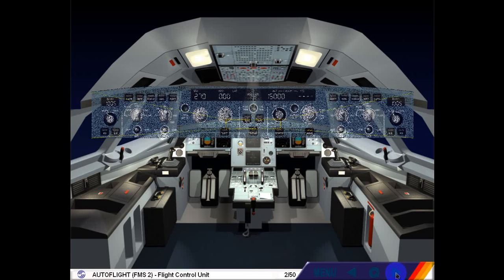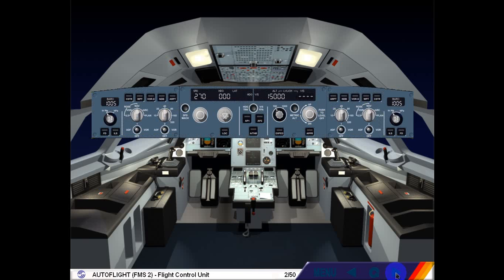The Flight Control Unit, or FCU, is the short-term actions interface with the FMGS. It is used to arm or engage the guidance modes and to select their associated targets. It is also used to set the autopilots, APs, and/or autothrust, ATHR, on.